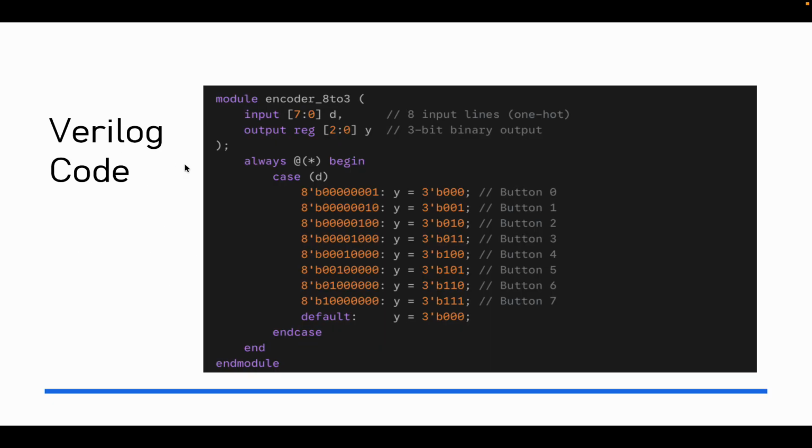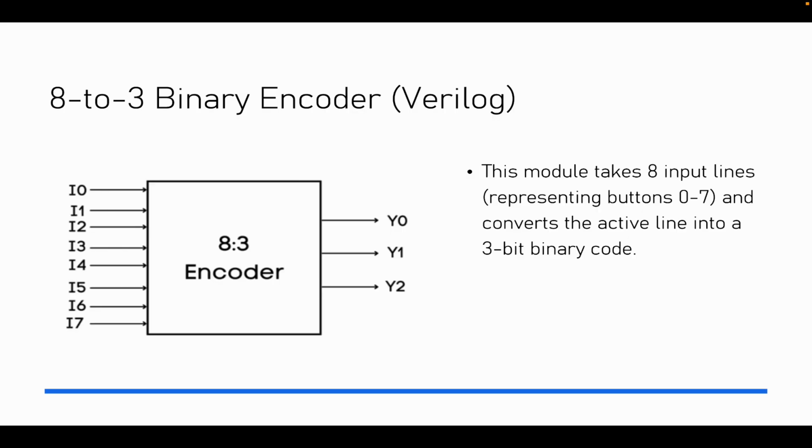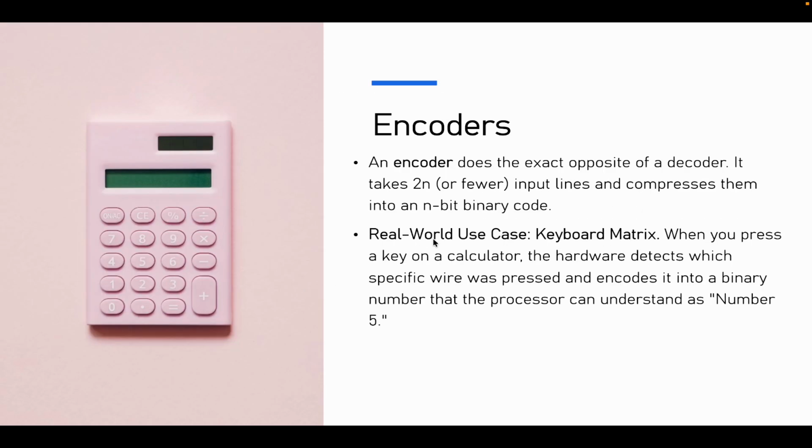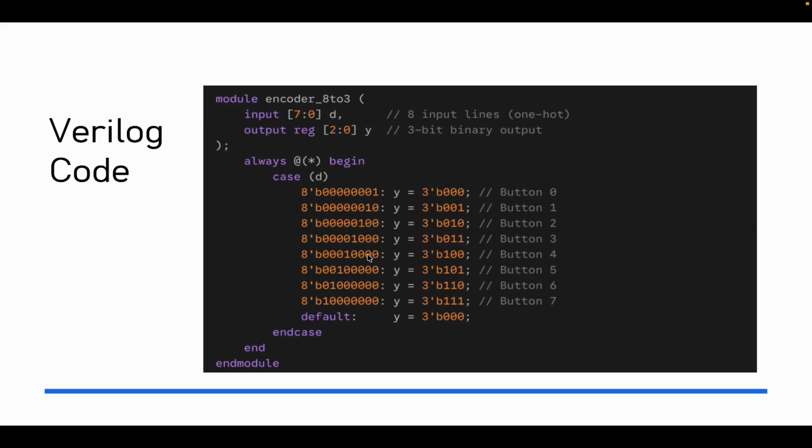But in this thing, do you see any problem? Okay, let me consider this simple case. Here, what happens is this is a kind of a tricky thing. You need to carefully listen to it. What if I press 5 and 6 together? Here, only one button is getting pressed. It's okay. But suddenly I decide, no, I want to have some fun. I'll press 5 and 6 together. That time, there becomes a latching. It means we don't get any output, right?